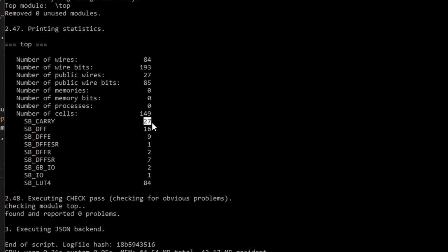Again, it's pseudo-random, and you can determine what the sequence is. But of course, if you want to implement something like a countdown timer, then you need to know what to set your shift register to in order to get the right value, when you clock it, however many times you're going to clock it.